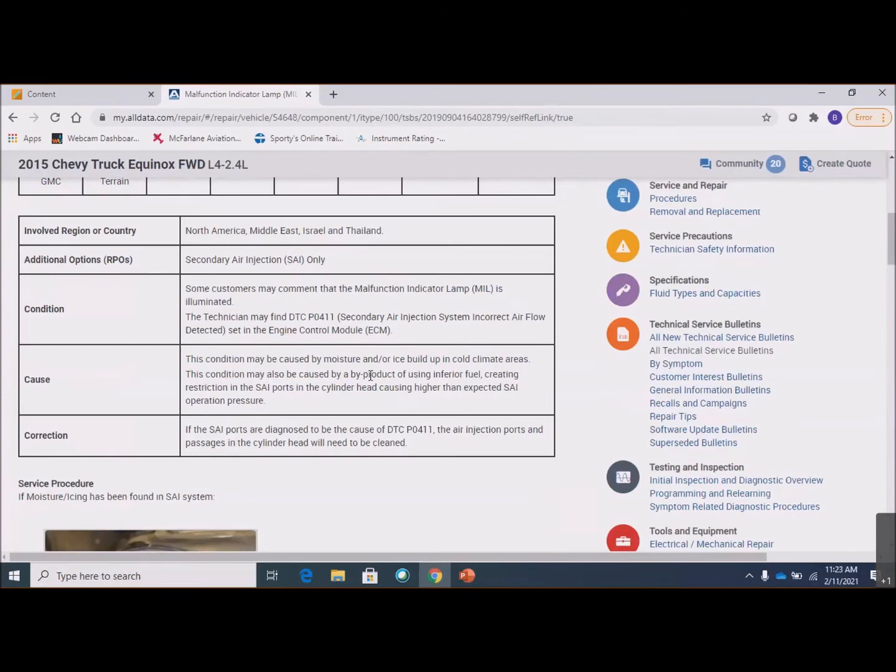These control valves, when they open, expect a certain flow and a certain pressure. Now, why we got the correct pressure on the diagnostics, I don't know. I'm wondering if there isn't an additional diagnostic for airflow here.